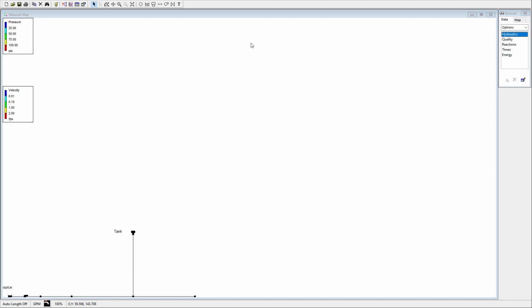In EPANet, there's some background stuff you can use, a backdrop they call it, but that's limited to a bitmap, which gets kind of clunky because you're limited to roughly half a gigabyte, and half a gigabyte for a bitmap just does not cover a very large area in high enough resolution. You can also use a Windows enhanced metafile, which isn't really much better from my experience.